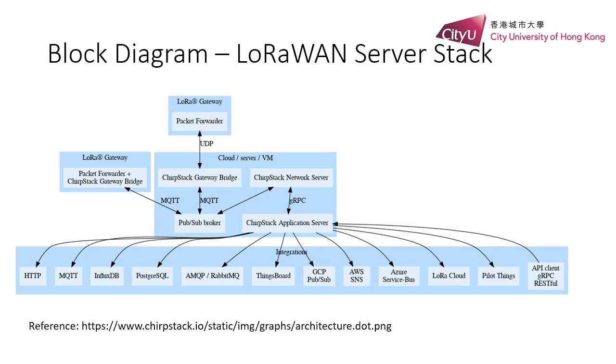The gateway will transmit data to network server by MQTT, then forward to application server. The application server provides lots of APIs to get payload. This implementation is compatible to LoRaWAN Regulation 1.1.0.